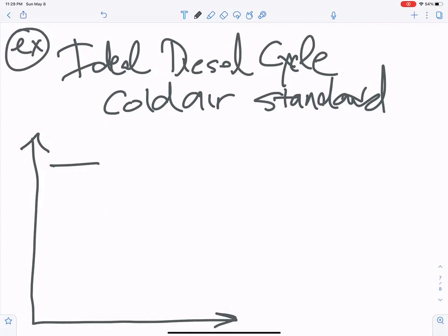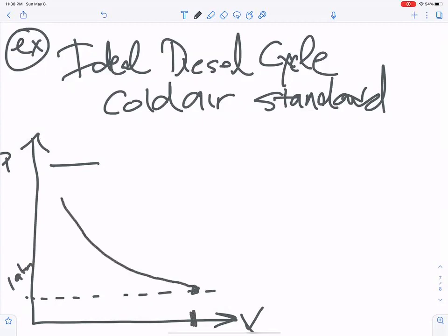Okay, so the standard diesel cycle, oftentimes you start at 1 atmosphere, 1 ATM on this PV diagram. So starting here at the biggest volume, bottom dead center, you'd go into this compression stroke all the way up to the highest pressure. This would be 1 and 2 here.